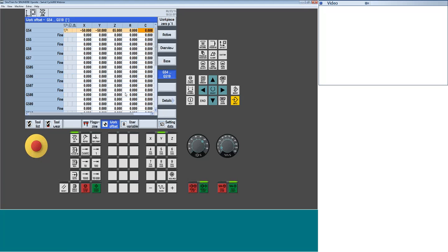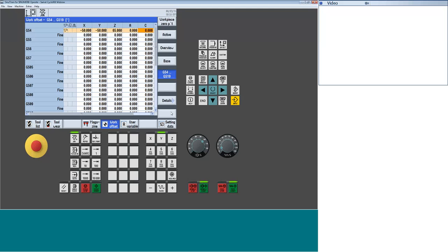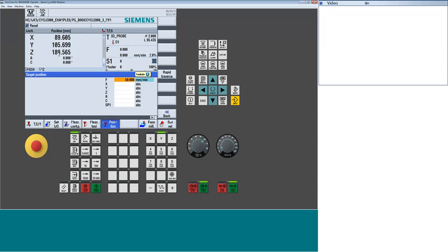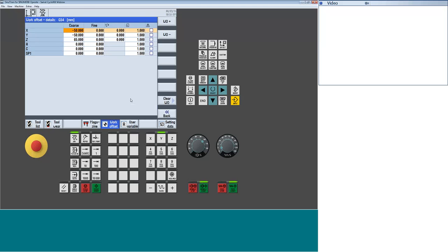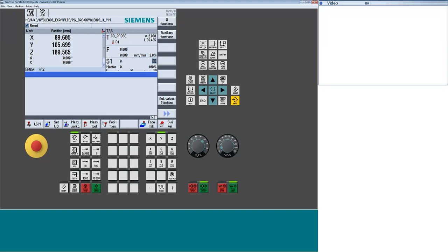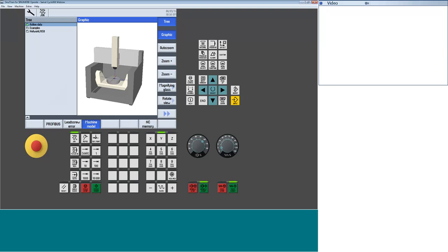So if I want to clear everything out, certainly the final stage I would do, I'm just going to manually zero out all these calculated values. Now we come back and bump. Why do I still have a rotation? Bear with me one sec. Did I miss one? Nope. A lot of times I will zero everything out with the swivel cycle and then shut it off again. And that's the final. So now I have no symbols. Everything's back to the normal machine 0. If I jump back, I see I'm still sitting at the same point I was just at.